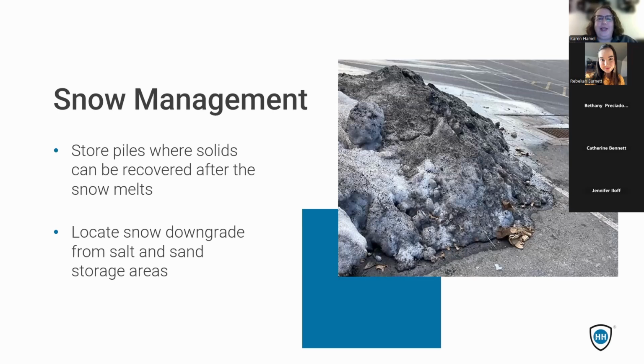This is in the Northeast, where we're starting to look at things chilling down, and we could literally have snow at any point now. So are there ways that we're managing our snow? This is a picture that I took at an industrial facility, and this was in February. What you see there in the snow pile is a lot of anti-slip that had been added to the parking lot just to help people with traction. And of course, there was probably salt in that pile from the ice melt that had been added to keep the parking lot safe. But you can see there's a lot of particulate there. And where's that particulate going to go? To that nearest drain if we don't have some way to stop it.